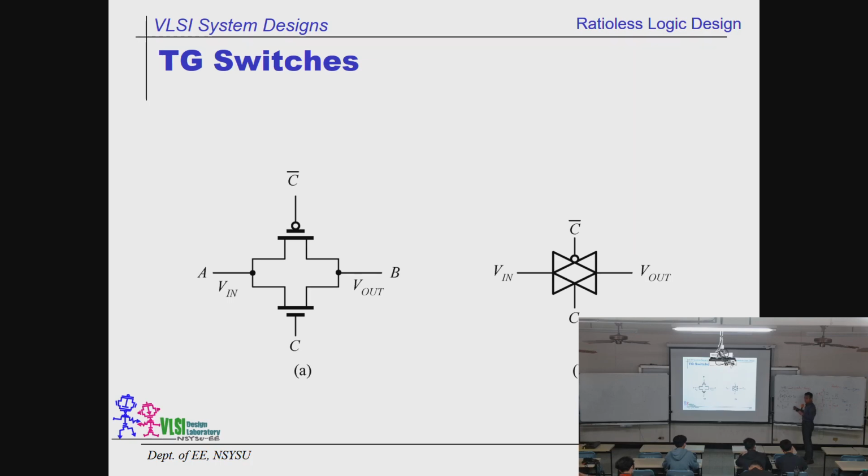Is that understood? So when you learn how to design the inverter, the next step you should know is that inverters can be used to create or design buffers. The only difference is how long a delay you need. The delay is based on the number of stages and the delay of a single-stage inverter. That's all for the buffers.